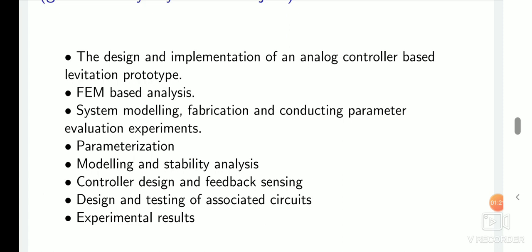What we have discussed till now is the linear controller. The system actually was nonlinear. We have linearized the model at a particular, desired, suitable operating point, and then using Taylor series expansion, the linearized model has come. On that linear model, we put all the parameters at the operating point, and then we got the transfer function, and then modeling, stability analysis, etc. start.